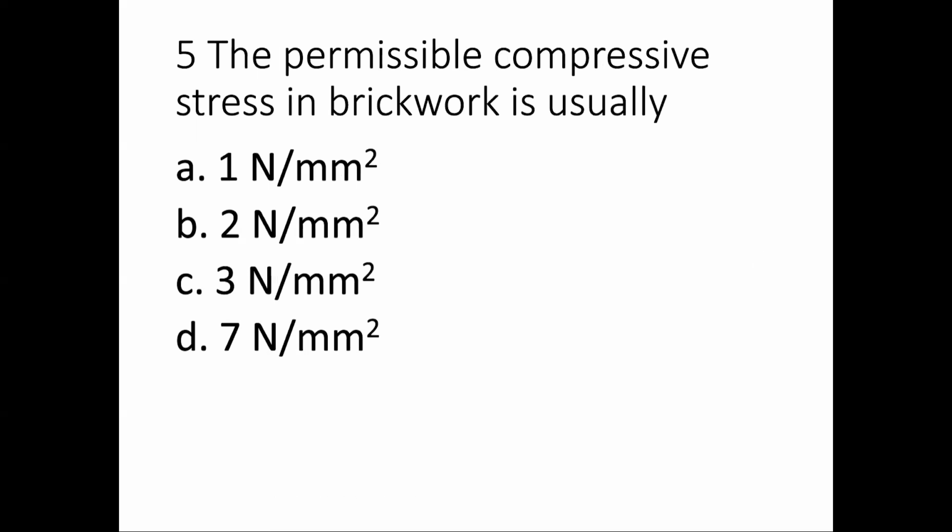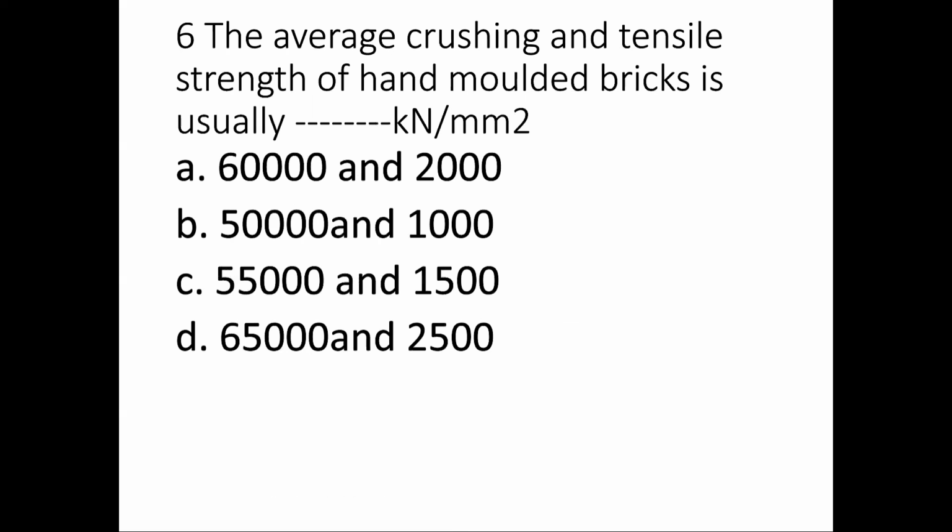Next question. The permissible compressive stress in brickwork is usually? Answer is 2 Newton per mm square. Sixth question. Average crushing and tensile strength of hand molded bricks is? Answer 60,000 and 2,000 kilonewton per meter square.